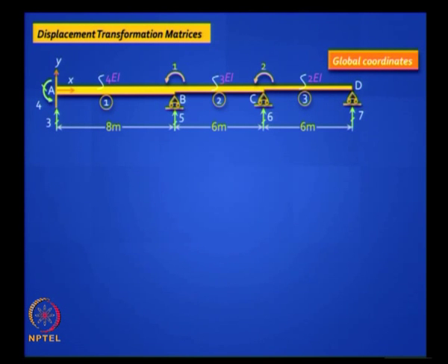We will do that. Why are we putting the restrained degrees of freedom? Because we want to find support reactions, that is the real reason. Also, in this case we also have support settlements in this problem. So you have to bring that into the picture, and let us look at that. We have 2 support settlements. Remember, B and C go down by 5 and 10 mm respectively. So you will label that as D5 equal to minus 0.005 meter and D6 as minus 0.010 meter.